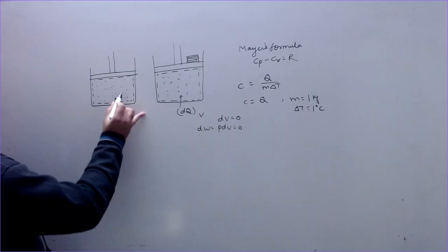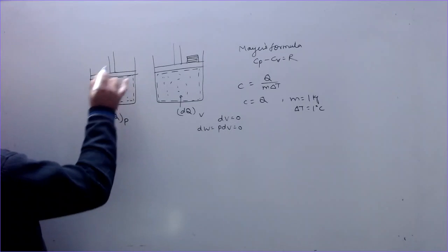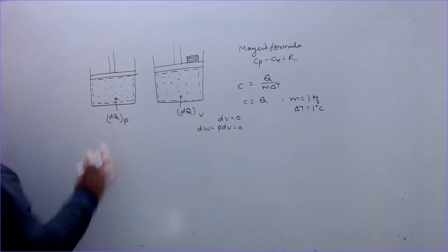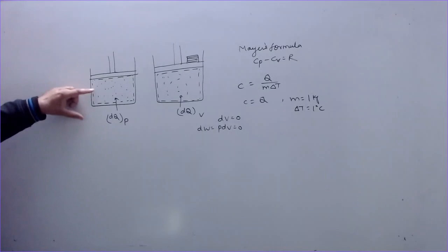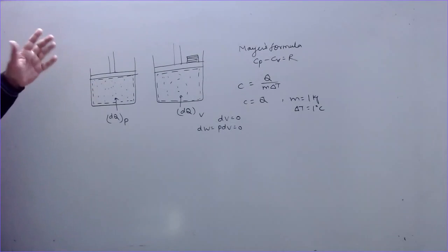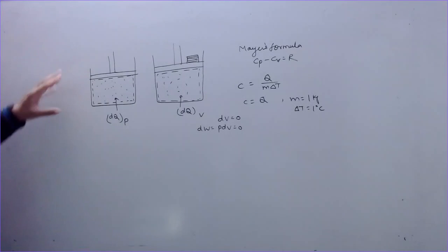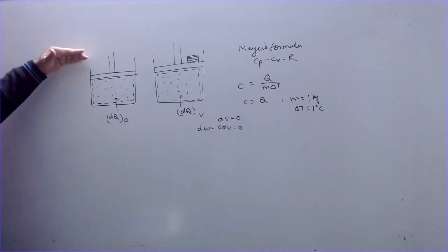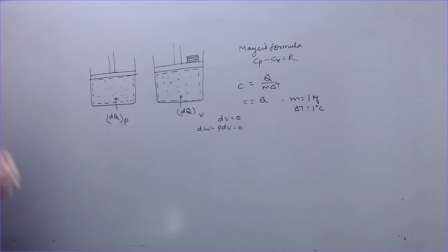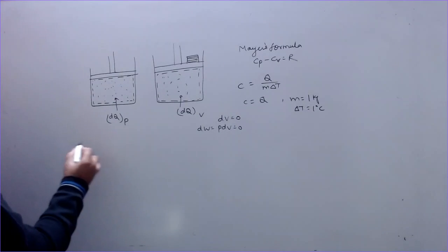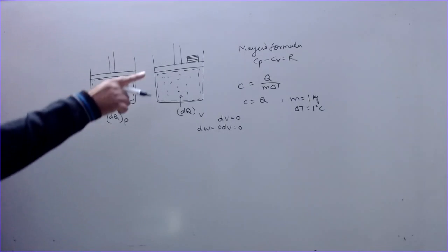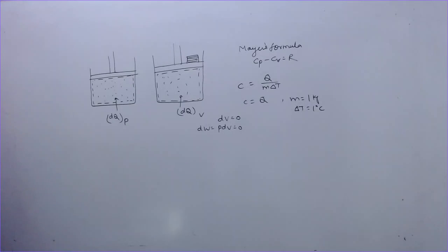And here, as you supply the energy, the energy of the gas increases. As a result, it pushes the piston outward. And as the piston moves, it keeps on moving until the pressure again attains the initial value. The system again comes to equilibrium. So this is called a constant pressure process because the pressure is maintained constant. The system will keep on moving until the pressure again becomes constant, which means equilibrium is attained. So the change in pressure is 0. We have to prove the relation we have mentioned here. These are the two types of systems.